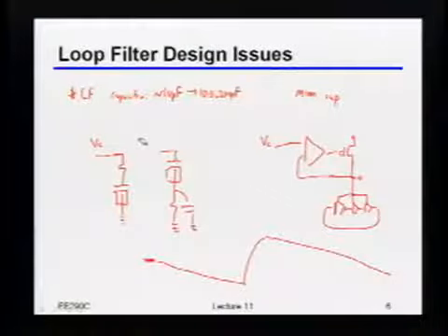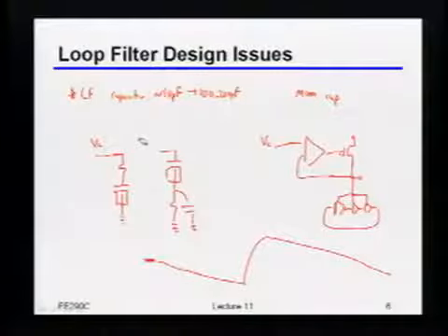No, but I'm just wondering, because when your VC is very low versus when it's very high, the cap is totally different. So yeah, okay, we're going to talk a little bit more about it, but it turns out if you really want to do things right, getting this VCO control voltage to be really, really small, meaning comparable to the threshold, you're going to have lots of other problems.